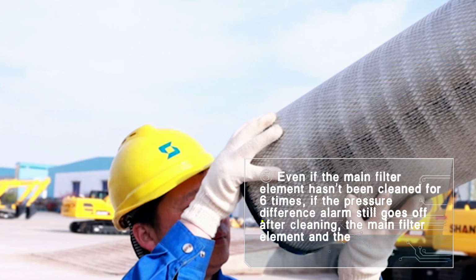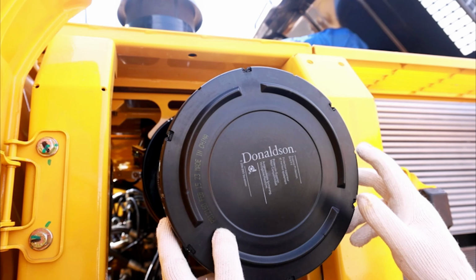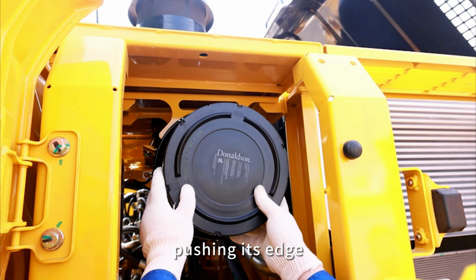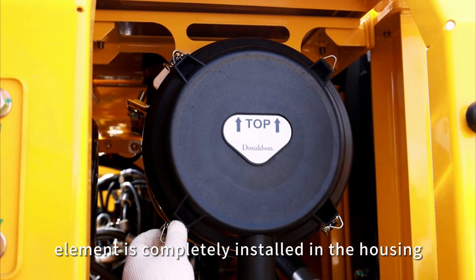5. Even if the main filter element hasn't been cleaned for 6 times, if the pressure difference alarm still goes off after cleaning, the main filter element and the safety filter element must be replaced. Carefully install the main filter element by hand pushing its edge, and confirm that the main filter element is completely installed in the housing.